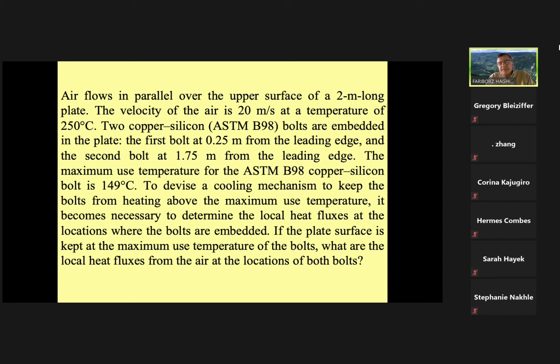In order to design that cooling system, we have to know how much energy is generated at that point. Therefore, what is the heat flux from the air at the location of this one? I have to know how much energy has been transferred from the air to this bolt. Then I design a cooling system to compensate for that heat.